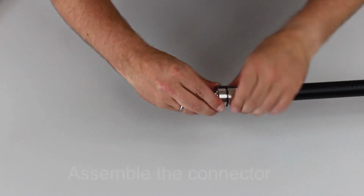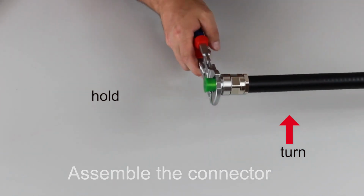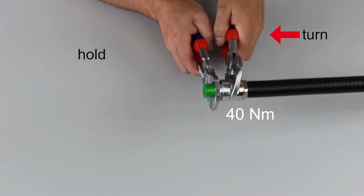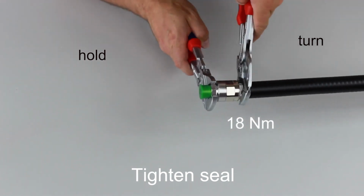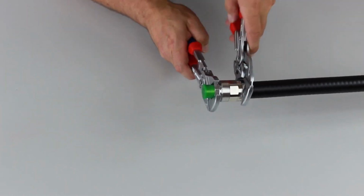To assemble the connector, attach the upper part and screw in the back of the connector by hand. Then use the pliers to tighten the connector. It is important that the head of the connector remains still. Repeat the same process with the seal, which must also be tightened with the pliers.